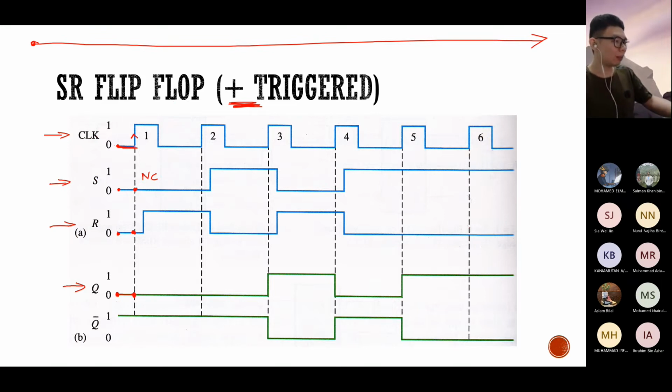After this rising edge is over, throughout all of this time, does the flip-flop work? It does not work at all. It just turns off, goes to sleep, and does not respond to anything. Even though you change this input and that input during this time, the output does not respond at all, because the flip-flop does not work until you meet another rising edge over here.